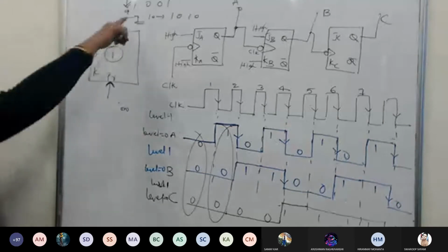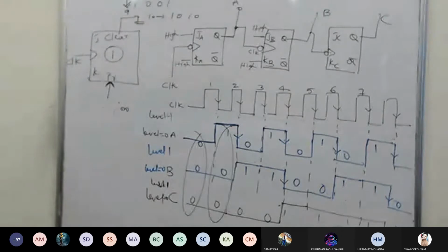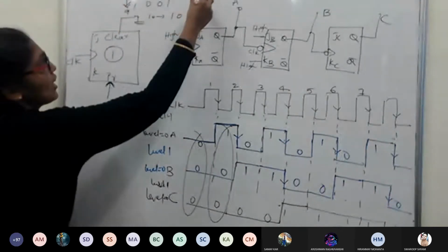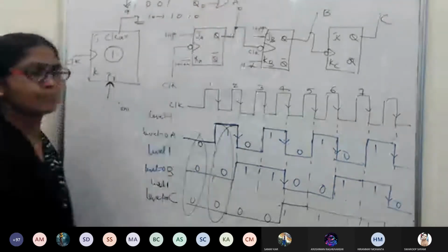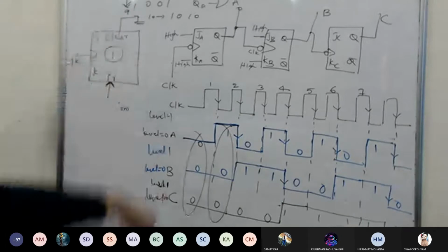So what I will do is follow what Ayushman is telling: use something external, gates, and stop the show. I will take this particular QA and QD every time and make it an AND gate. For every state I will make an AND gate. You just check: other than decimal digit 9, the rest of the things are all 0.